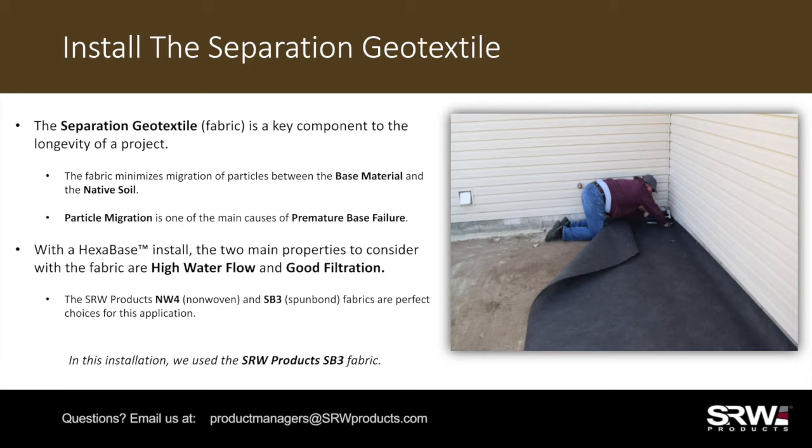The separation geotextile, or fabric, is a key component to the longevity of a project. This is because the fabric minimizes migration of particles between the base material and the native soil. This particle migration is one of the main causes of premature base failure under pavers.